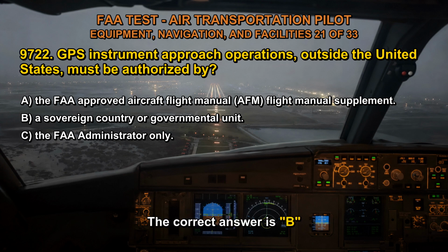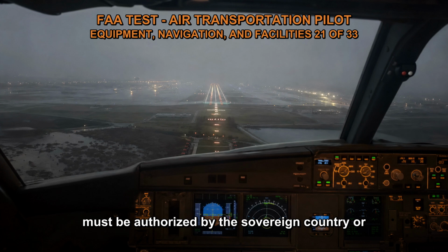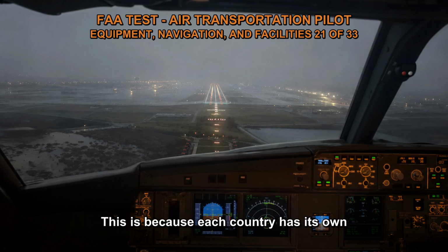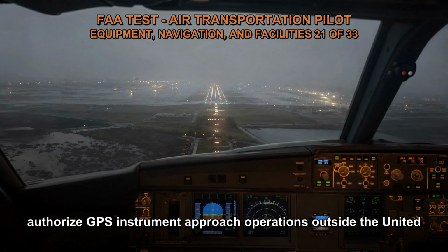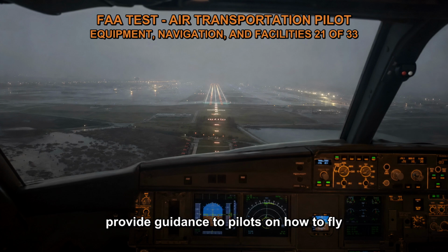The correct answer is B. GPS instrument approach operations outside the United States must be authorized by the sovereign country or governmental unit where the operation is taking place. This is because each country has its own set of regulations governing aviation operations. The FAA does not have the authority to authorize GPS instrument approach operations outside the United States. However, the FAA does issue AFM supplements that provide guidance to pilots on how to fly GPS approaches in other countries.